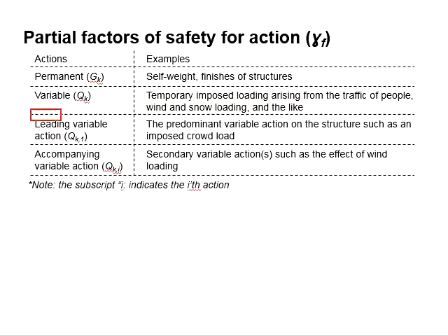There are leading variable actions and accompanying variable actions. The leading variable action refers to the predominant variable action of the structure, such as an imposed crowd load, and the accompanying variable actions are the secondary variable actions, such as the effect of the wind loading.